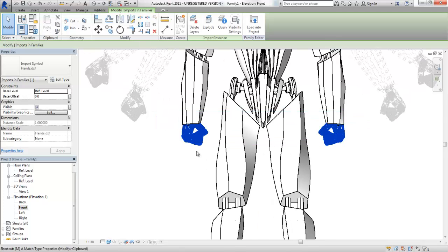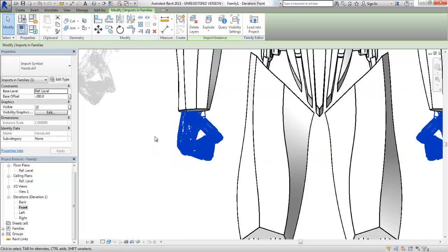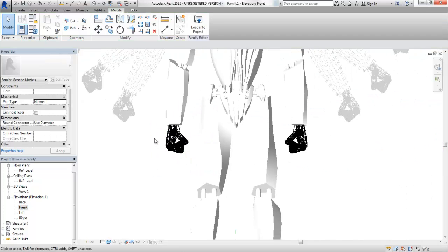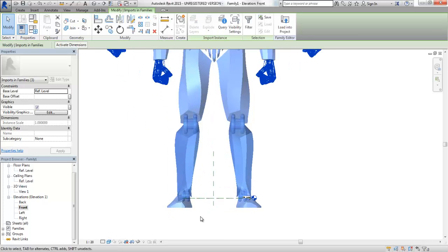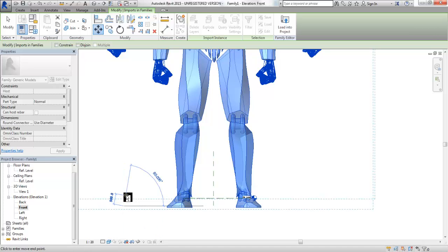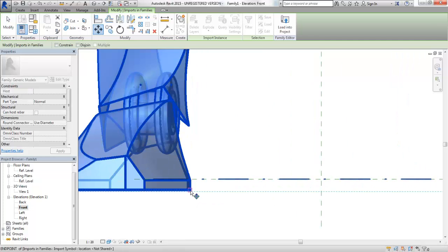And then we'll just MV. It looks like we're a little bit off. MV. That looks better. Now for now we'll have everything in there. MV. Let's go ahead and just move this up. Use our object snaps for a change.